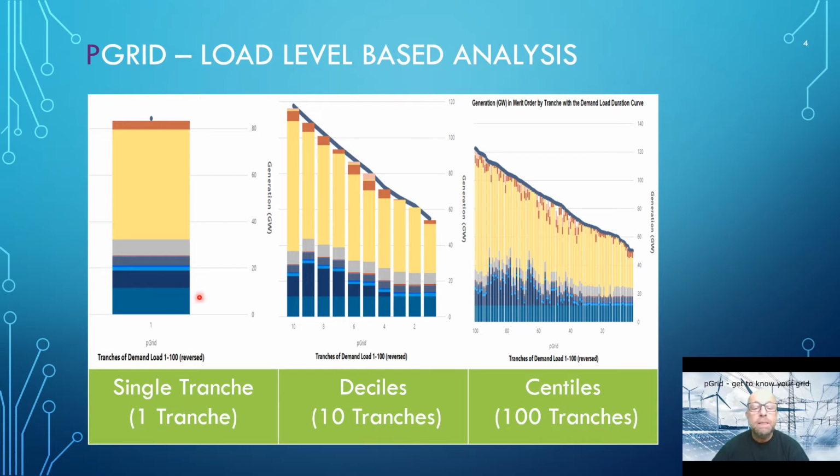And that energy would be provided by the generating assets that we've assumed, their capacities and their availabilities. And we would order them in order of increasing cost. So the cheapest guys go first, the most expensive guys go last, and that way consumers get the cheapest cost of energy. This guy down here is the lowest cost plant we have, which is the nuclear plant, and the one above it happens to be solar, and this one here is the large amount of wind that FES have assumed for this scenario. But we kind of know that load is not the same.